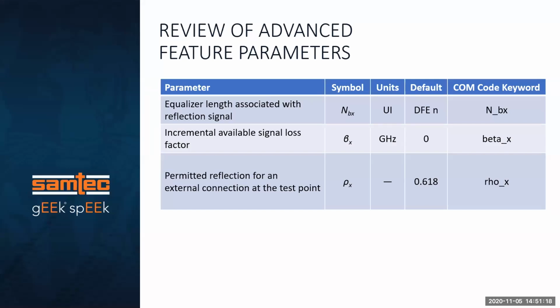So here's again these parameters. These are extra parameters, and these are required. And a lot of times we'll set NBX to 0, which makes the beta X and rho X parameters move. But we decided to lock these two parameters, beta X and rho X, down, to 0 and to 1 respectively. Originally, I'm going to talk about that in a minute. It does make sense, but they both sort of do the same thing.